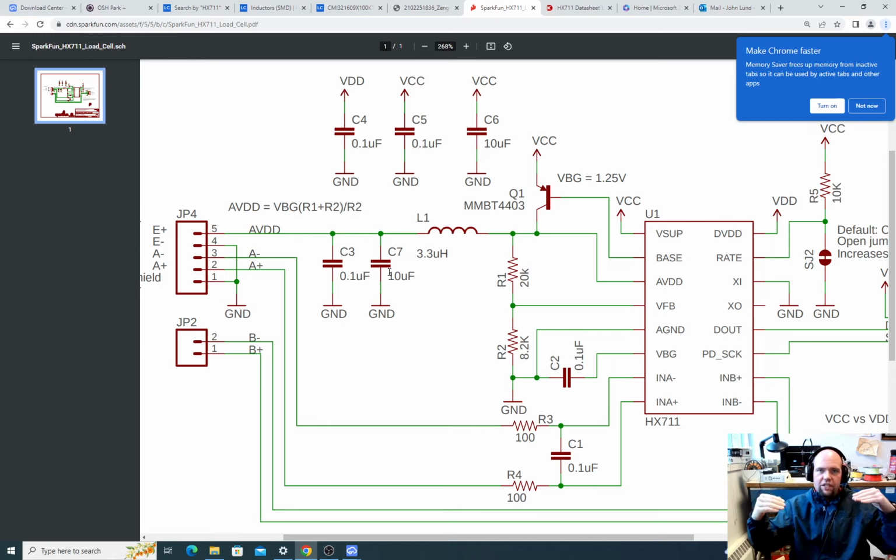So to actually function as the full 10 microfarads, electrons have to get all the way to the back end of the capacitor through that resistive metal, get up to the surface of that oxide layer, and find a matching pair of charges on the other side. Depending on how you structure your capacitor, those charged particles can't make it there that fast. Even if they're electrons, there's resistance in the metal. In electrolytic capacitors, you're not even using electrons, you're using ions in a liquid, which move very slowly compared to electrons. So a lot of capacitors have bad frequency response.